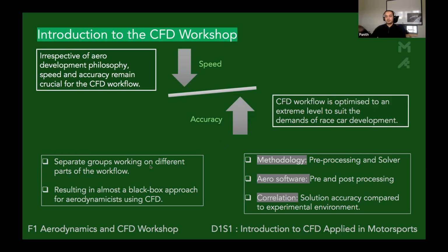You've got separate groups working on different parts of the workflow, the CFD workflow, which I'll introduce in the next few slides as we go through. It almost results in a black box approach for aero engineers that are using CFD, so they can focus on developing the geometry of the car and spend all of their time doing analysis of the results from wind tunnel, from CFD, from the track. A lot of data is gathered on the track as well.